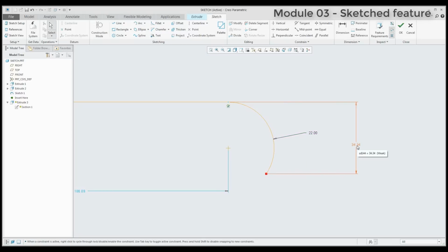This is the linear dimension, and the question is if we would like to create a different kind of dimension. You can create the dimensions, you can select the arc and then two ends of the arc and the middle button. If you see here, the system will create the new dimension for you, and this is the length of that curve. So you can see here the system will create a dimension defined by length.